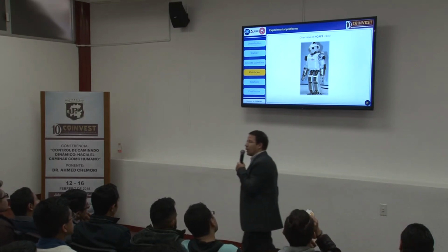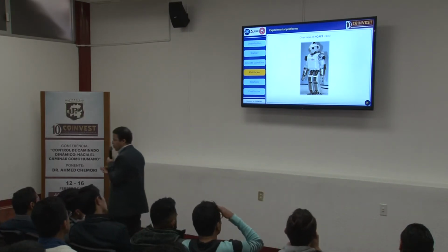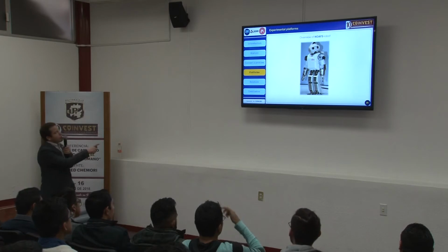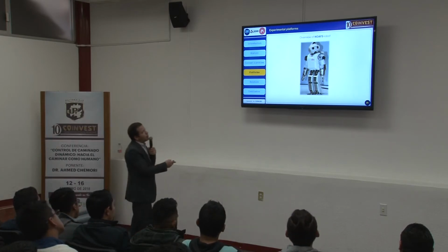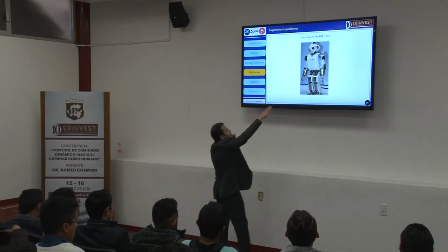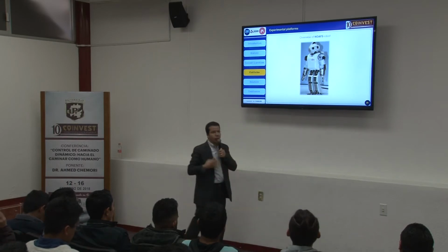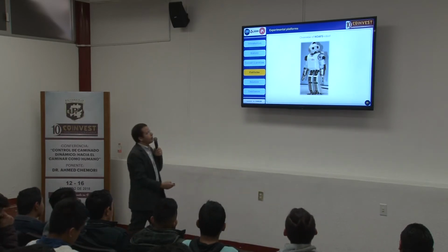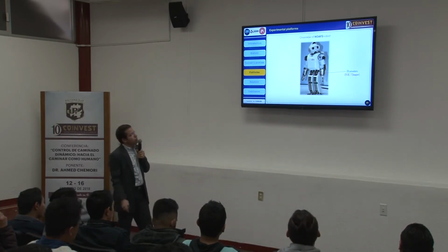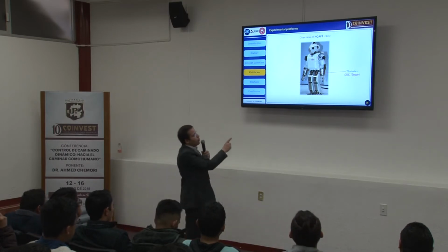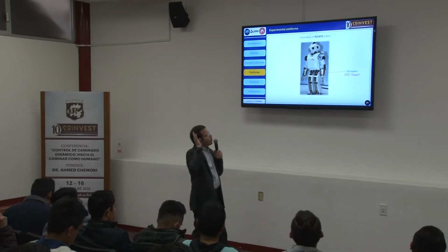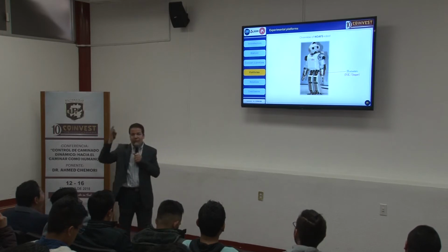The second prototype is a Japanese robot called HRP-3. As you can see, it's here. So it's a whole body robot. We have the 2 legs, and we have also the upper body, the torso, and the 2 arms. This robot has 28 actuators, 21 DC motors and 7 steppers.